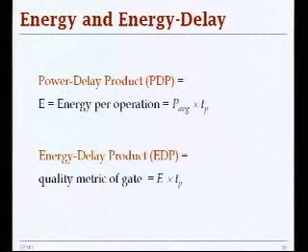So that is the energy per operation. You have energy defined as the product of your average power consumption and propagation delay. But the energy is constant, and that's good. So you can pretty much evaluate how much energy you need to spend to perform a certain operation and evaluate the cost of performing that operation.